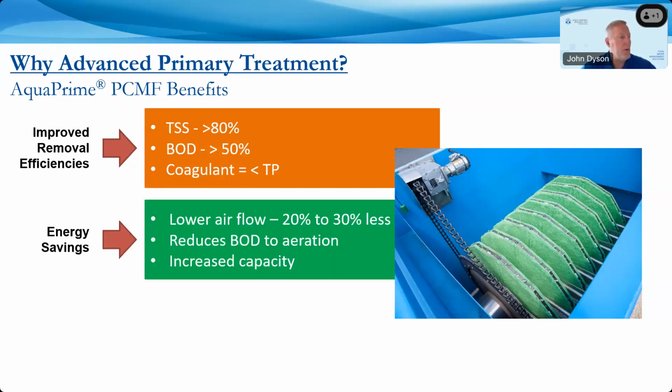What does that mean to a treatment facility? Well, what it means is if you're trying to just do this with an existing facility with no capacity increase, you could save on your energy costs, which we know aeration is the largest energy cost within a wastewater facility. So that could be a 20 to 30% energy savings. So that's very dramatic because of the reduced BOD and increased BOD removal provided by the technology.